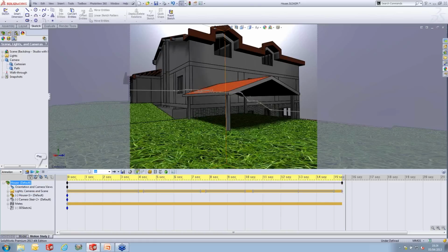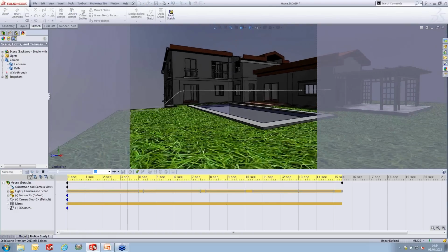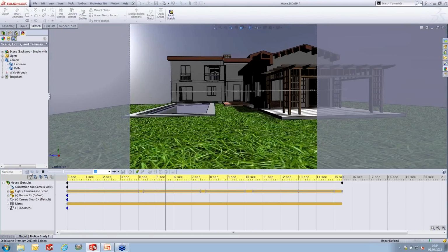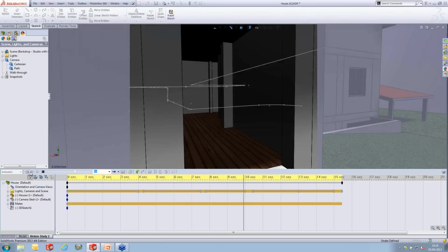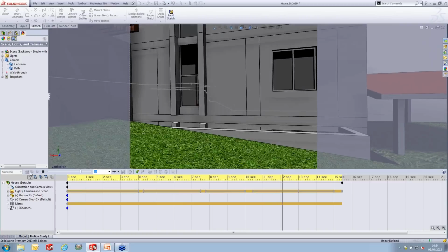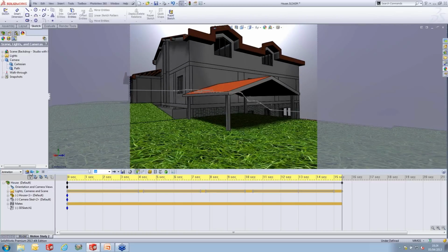And if I just play that through from the start, we can just analyze whether it's got the right timings. We can move any key points to relevant positions. So you click play from the start, and it'll just generate and have a look through the section of the animation you created so far. And you see by putting in the slight pauses, it just gives you that bit of a stop between the different types of animation. But you see at that section, I just move straight across. So that looks quite effective already. And that is just simply by moving the camera around the model.